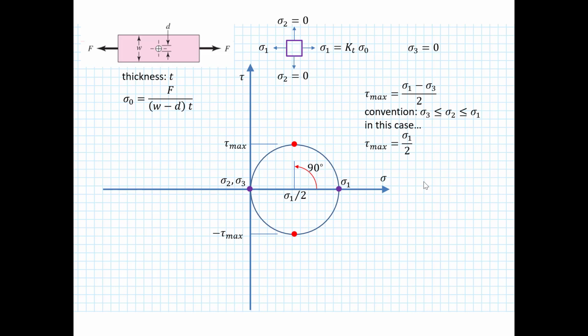One of the things I like about Mohr circles, it gives you a chance to look at a particular loading from a different direction. And I've identified a red direction here that's 90 degrees offset from the sigma 1. And then the other one here is offset 90 degrees from sigma 2, sigma 3. And what that looks like, since Mohr's circle is a double angle, that's actually related to 45 degrees in the real stress element. So the 45 degrees here for this face and this face corresponds to that point.